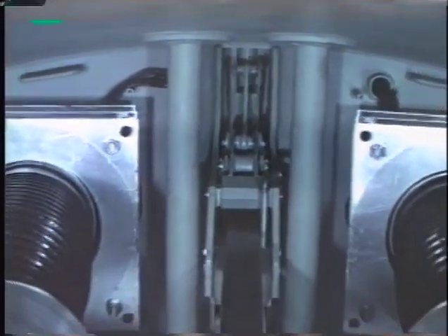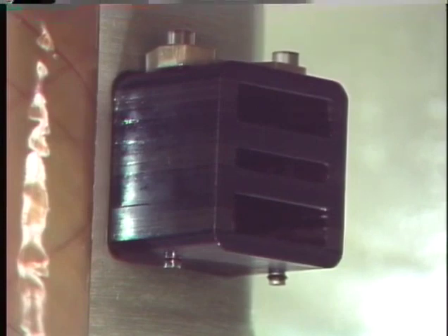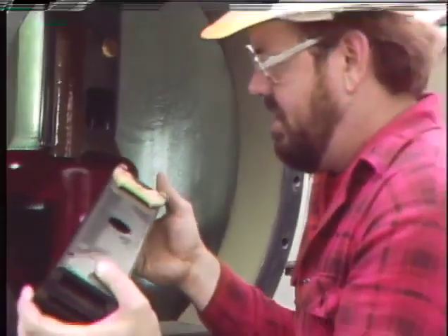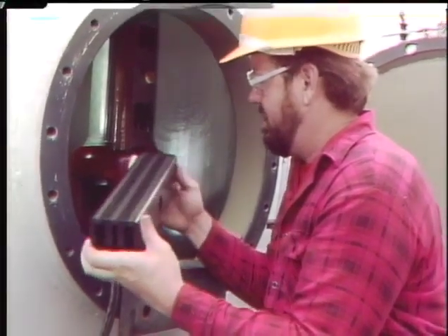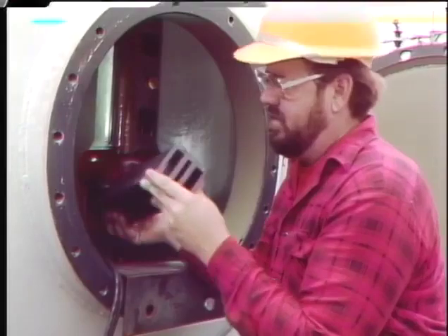Other general breaker checks that are made include inspecting the mechanisms for wear or damage. A task that applies specifically to oil breakers is inspecting the interrupter grids. To allow a thorough inspection of the grids, they are typically removed from the breaker. Then the grids are inspected for signs of heat damage or erosion, especially in the areas that surround the arcing contacts. If damage is evident, the interrupter grid may need to be replaced.